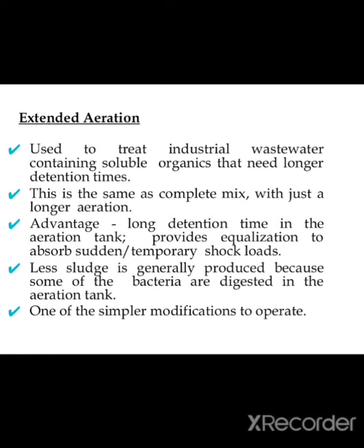The main advantage is the long retention time in the aeration tank, which provides equalization to absorb sudden or temporary shock loads. Less sludge is generally produced because some of the bacteria are digested in the aeration tank. It is one of the simpler modifications to operate.